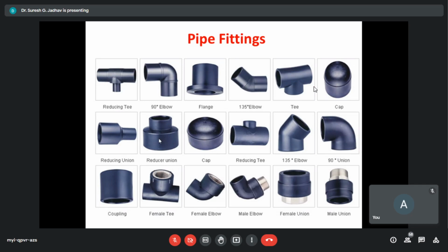female connections into which different size pipes can be fitted with the help of reducers. It may also be made with one connection eccentric for free drainage of water. So here with the help of this reducer we can connect pipes, but we can slightly reduce the piping size. That kind of fittings are used in piping systems.